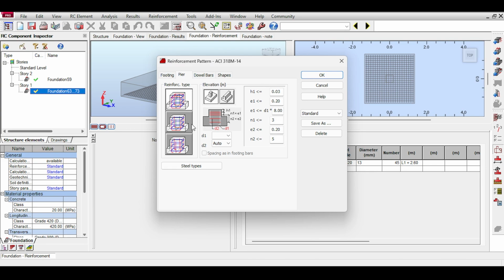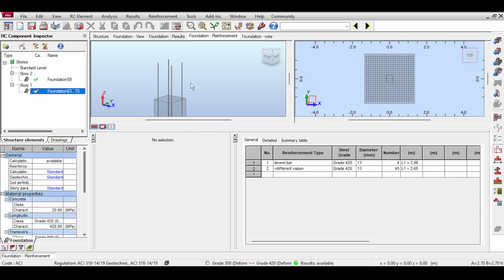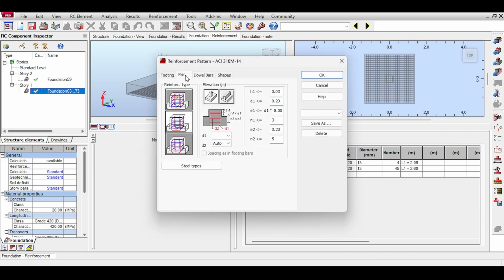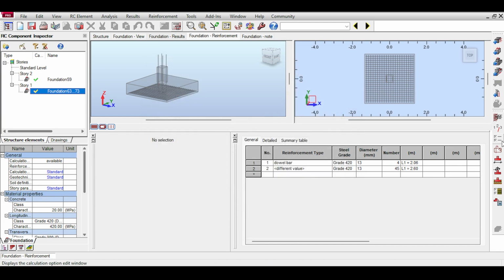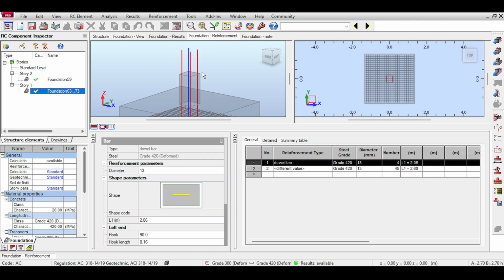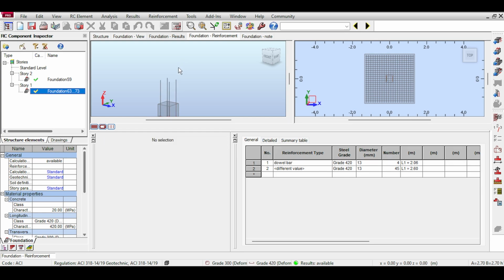And I think the way I was solving it is by clicking on this steel and asking it to make some dual bars and then hitting OK. Oh, it's still unable to provide reinforcement. Well, joke's on me. I have to keep trying changing the pier here, changing those reinforcements, and playing around with the reinforcement details in the calculation option. However, that's not my case here because I'm interested in the reinforcement of the foundation. The reinforcement of the pier is taken from the column. Remember, the column is already reinforced, so you can just copy-paste the reinforcement of the column.